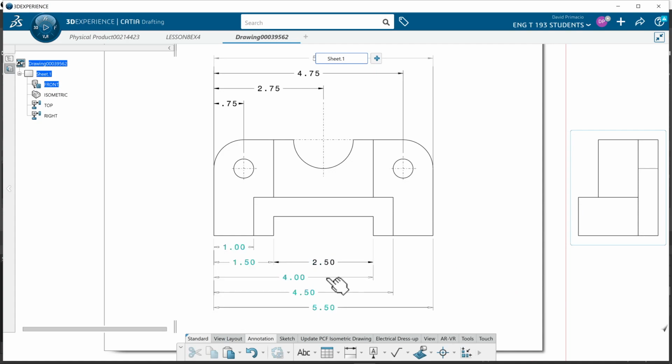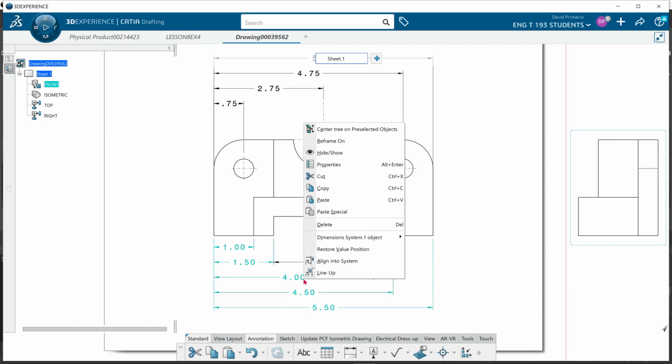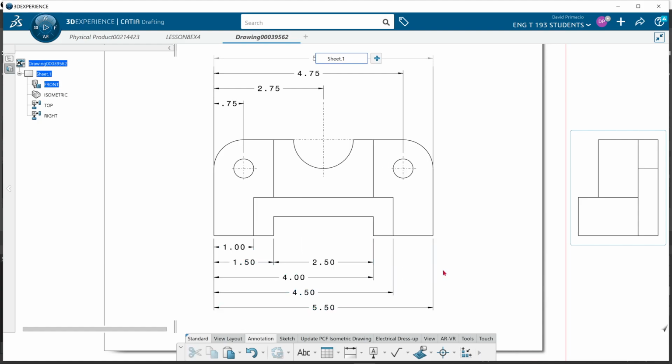So this 4-inch dimension, if I leave that in there, I'm over constraining this. I'm double dimensioning. So I need to delete that one dimension. Now I just ungrouped it, so I lost my links to this being stacked. Okay? So I shouldn't have done that, but what I do want to show you is this dimension here is now controlling this. So the worst case scenario, it would go down to 2.47.